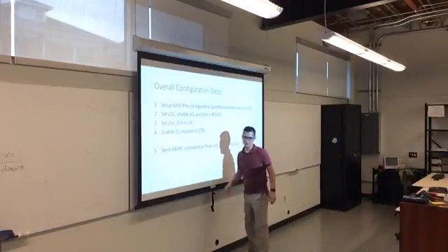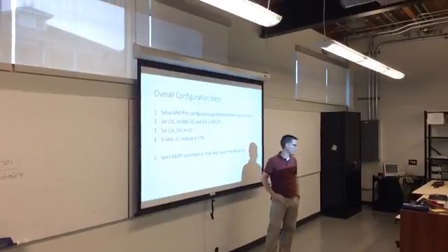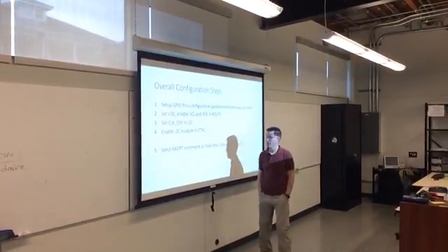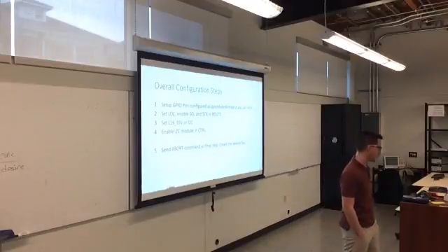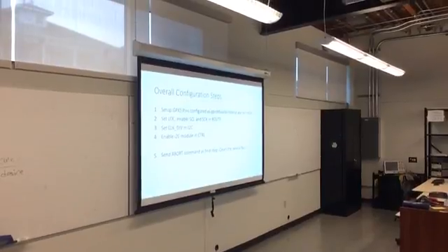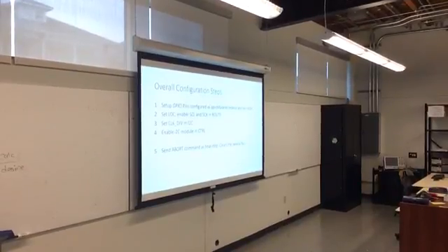Once you've configured it, the first thing you should do is send an abort command, because that stops everything on the bus and resets it to a known state. So you're going to have a function called setup, and you do all of these configuration steps, and once you're done, send an abort command to clear the bus.